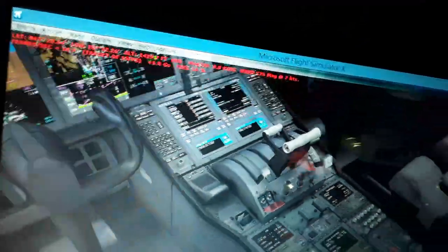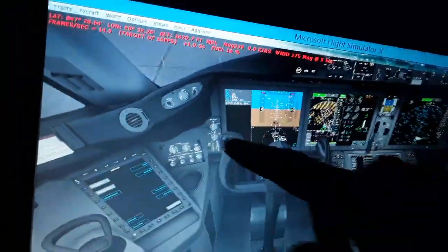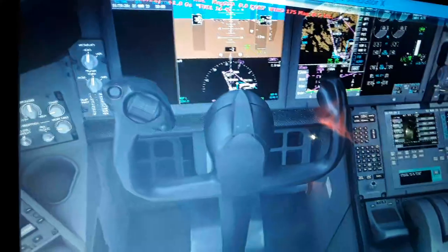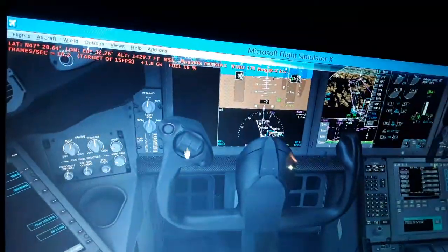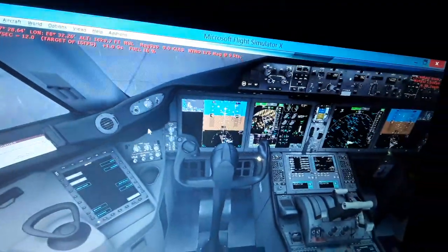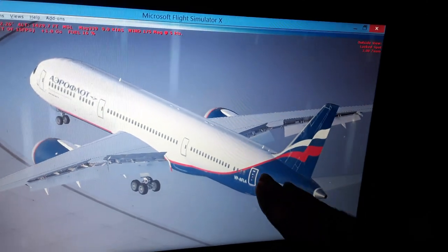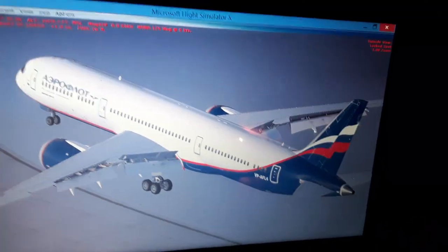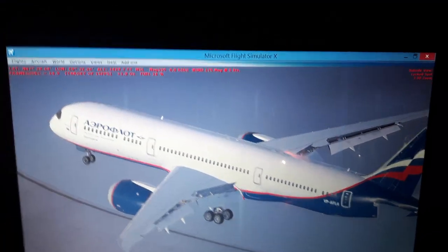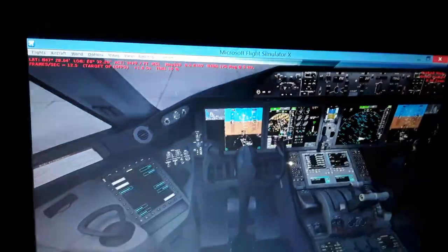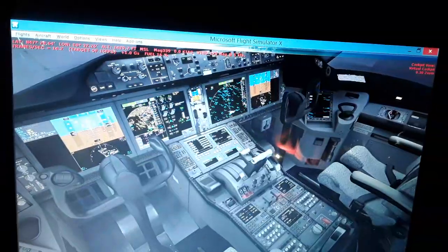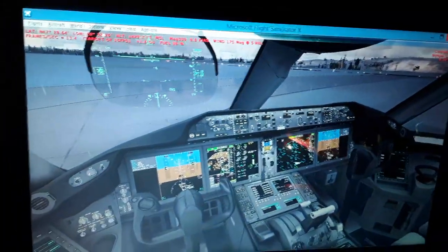We'll have only the manual trim through the control wheel over here, which is always variable. So you can trim up and trim down the horizontal tail of the aircraft like this during the whole flight. So it will balance the aircraft either nose up or nose down using the aerodynamic forces generated from the wings, from the airflow as we fly.